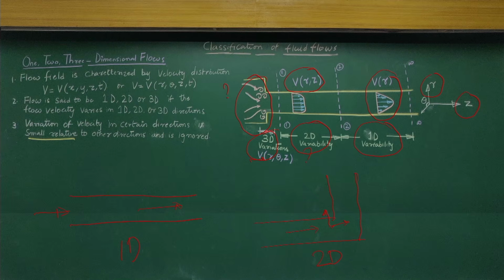Now, before going to the next levels, what I want to say is that as engineers, whenever you get a fluid flow problem, first try to understand these classifications: whether the flow is steady or unsteady. That means, does the flow vary with time or not. So first you talk about the time variation, steady or unsteady. The second: do you expect the flow Mach number to be more than 0.3? Then incompressible or compressible will come in.